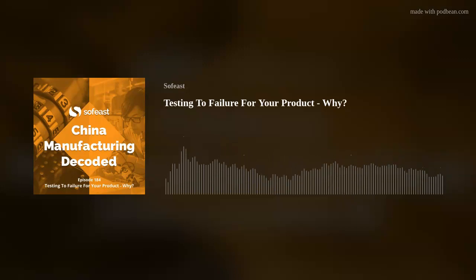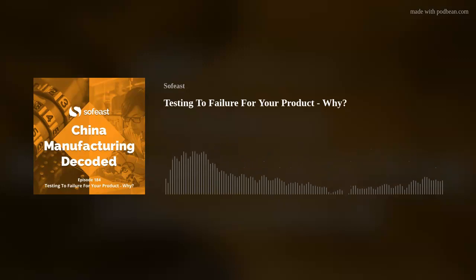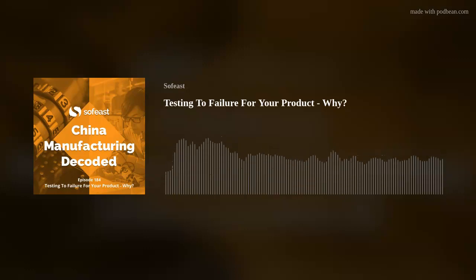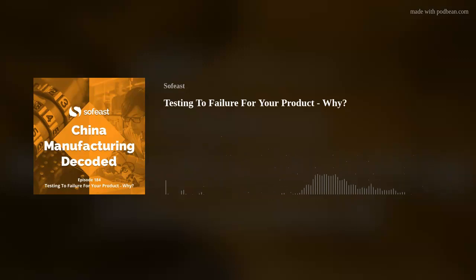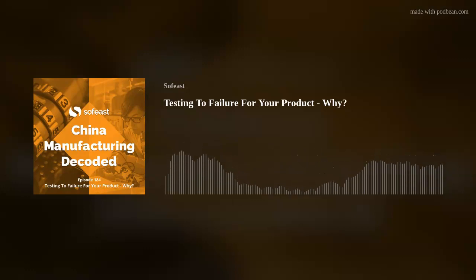So what's next in terms of methodologies then? Well, the next thing that you could do is high stress testing. This type of testing is mostly to check and see if any of your components, transistors, caps, resistors, active parts, passive parts, are going to be okay under a high stress environment. And high stress could be anything. It could be excessive voltage, excessive current.